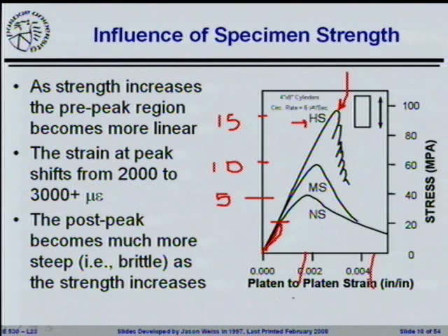All right. The other thing you'll see that's a big difference is you will see the normal strength concrete tends to have a much more gentle slope after peak than the high strength concrete. And in fact, the student who was doing a lot of this work, the whole thesis was on how you control the behavior of the concrete when it fails.